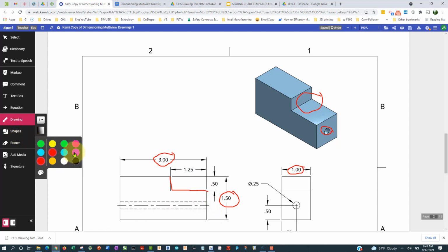let's see, what am I going to do? I'm going to start here with the line tool, and I'm going to come over 3 inches, and then come up 1 inch, back this way 1.25, up 1/2 inch, and back here. What is that, 3 minus 1.25, or 1 3/4? Although the geometric constraint of being right above this point will alleviate the need for me to actually dimension that out, and then I'm going to come back here. Okay, so let's start that. 3, 1.